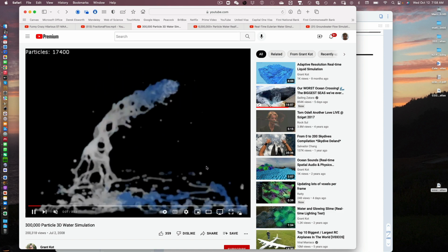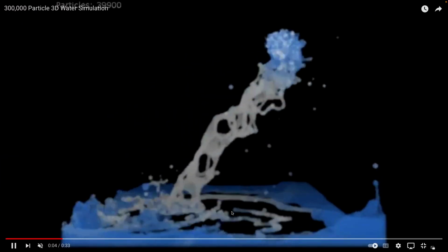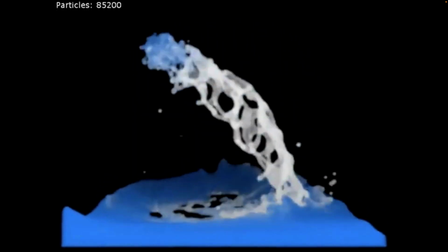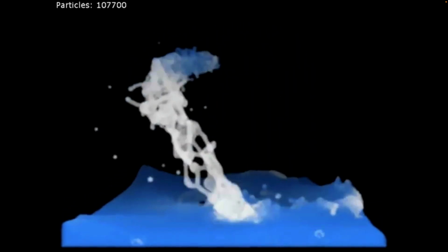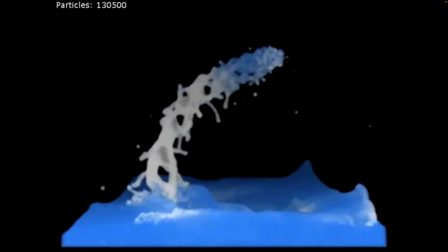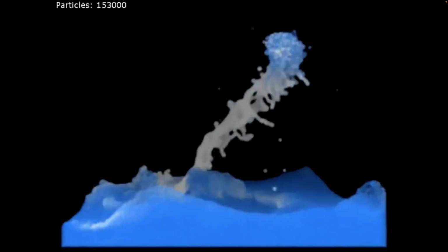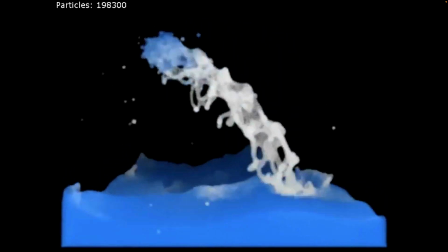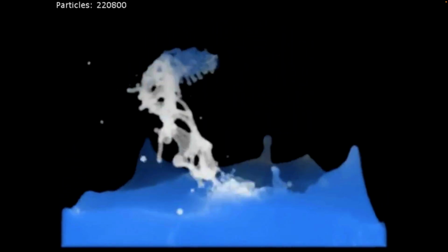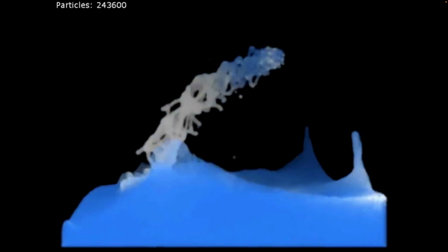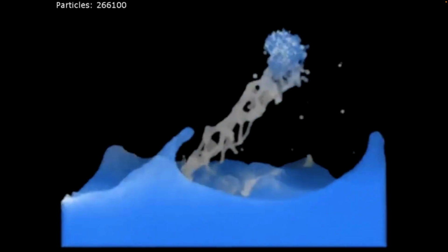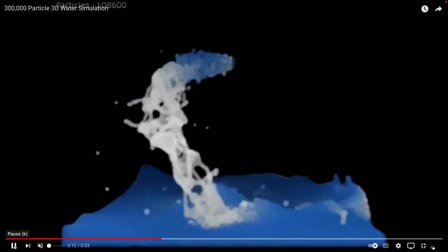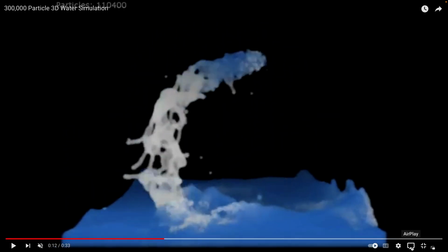Yeah, okay. Smooth particle hydrodynamics was the name, SPH. And what it does is it treats each block of fluid as a particle that's flowing through the system. So you can imagine this as being a hose that's squirting out a whole bunch of marbles. But those marbles, instead of being glass, happen to be fluid. And when they meet other marbles, they coalesce in some way and become this fluid at the bottom. And so it's just a technique that's using the idea of representing the fluid as a bunch of individual particles.